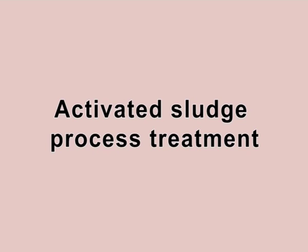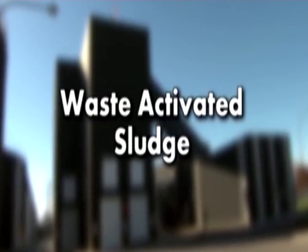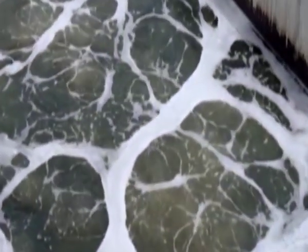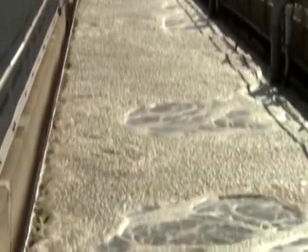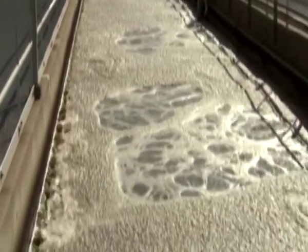In an activated sludge treatment system, an acclimatized, mixed biological growth of microorganisms is brought into contact with organic material in the wastewater in the presence of excess dissolved oxygen and nutrients such as nitrogen and phosphorus. The microorganisms convert the soluble organic compounds to carbon dioxide and cellular material, that is, new biomass. Oxygen is obtained from applied air, which also maintains adequate mixing.